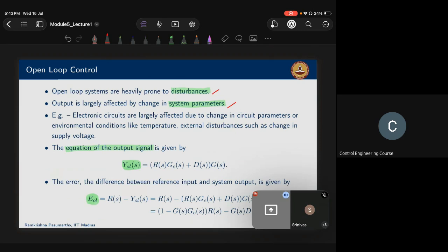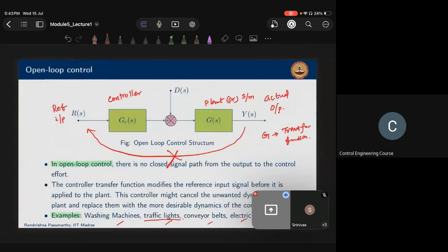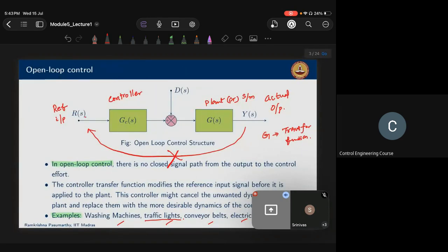Now if you see this open loop output equation, R of S is given as input to the controller. Here we get the control input, U of t. Then the control input is given to the summation, where D is the disturbance. The disturbance enters here and changes this control input a bit. After the modification, in whatever way the disturbance does, let's call that U tilde.